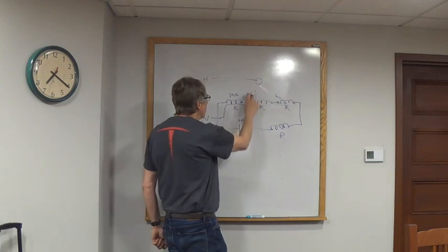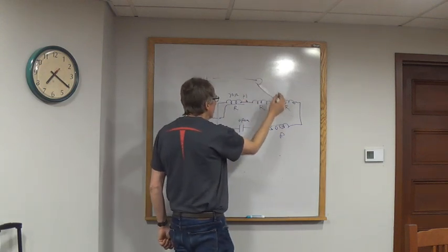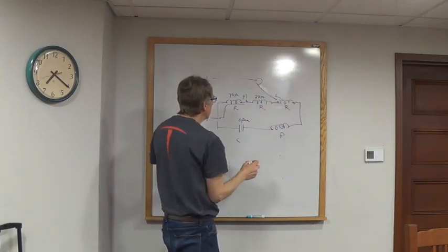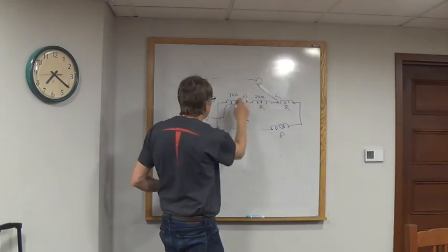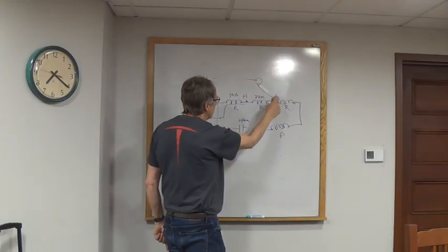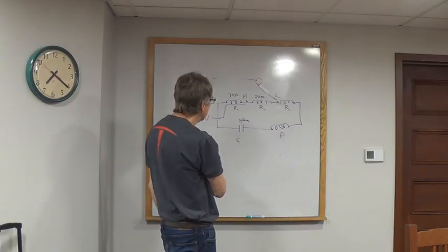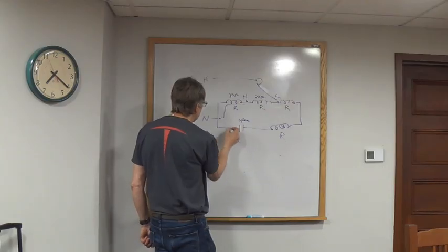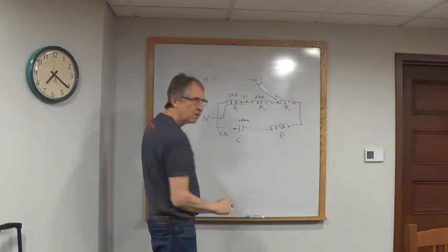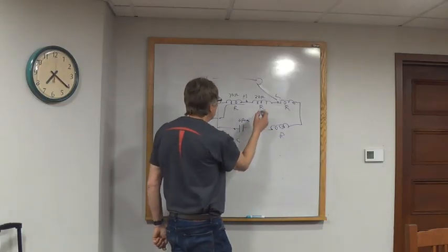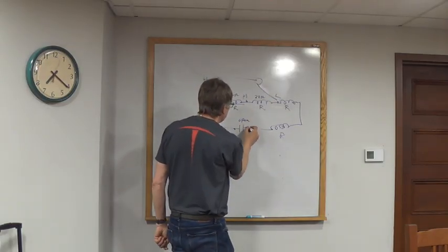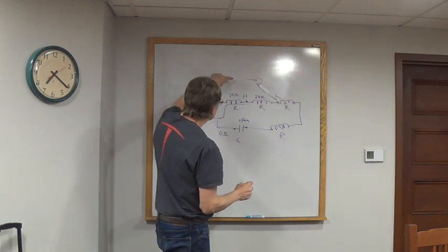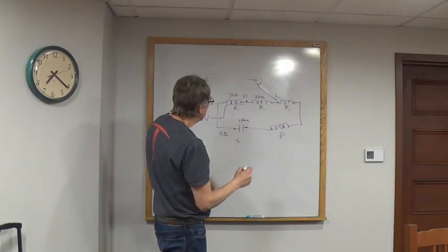Then you'll switch your fan to low. Notice now, say this is maybe an additional 20 ohms. When it's on high, you'll measure 70. When you set it to low, you'll measure 90. Another thing you can measure is from here to neutral, you should see 0 ohms. It's a direct connection. And if you measure from hot to the other side of the capacitor, now you've got a path that goes this way.